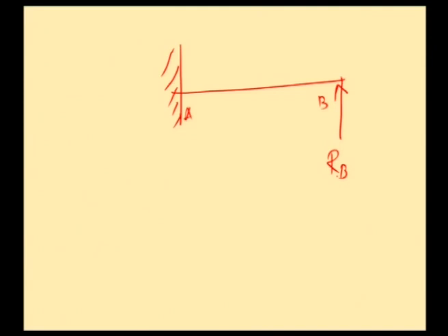As we discussed, a propped cantilever is statically indeterminate to 1 degree or first degree, and we will be treating R B as the unknown. As we discussed, we have excess reactions which need to be found using an extra equation.